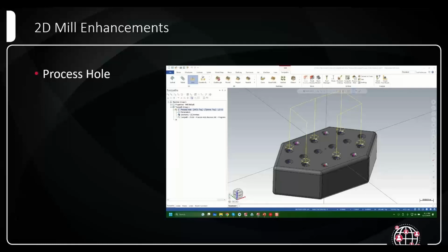Biggest caveat I see there is that you have to grab the entire hole feature. Therefore, they have to be defined as solid holes. Thankfully, with the last few years of enhancements, you have the ability to identify solid holes from other CAD sources or from a dumb solid. So it definitely makes that part a lot easier. But making that solid hole feature or identifying that solid hole feature is very important for that step for it to understand what the depths need to be for each of those. So definitely look forward to that and playing around with that in the future.